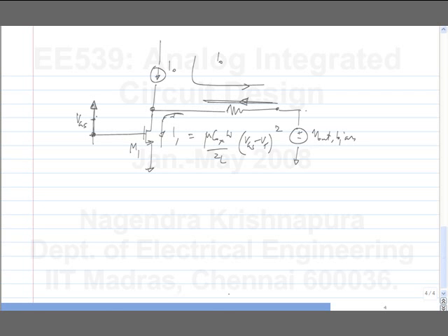Now you are most of the time interested in driving symmetrical signals like a sine wave. So bottom line is, overall the current here is limited by I0. This is always true of class A amplifiers. A class A amplifier is driven on one side and there is a bias current on the other side. The bias current is a hard limit. On the other side you could have possibly pushed more current.